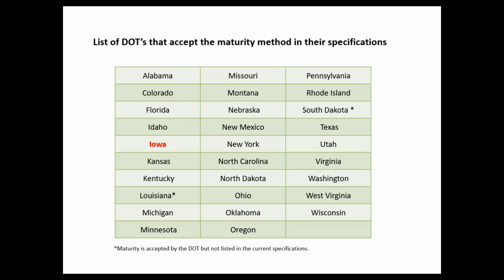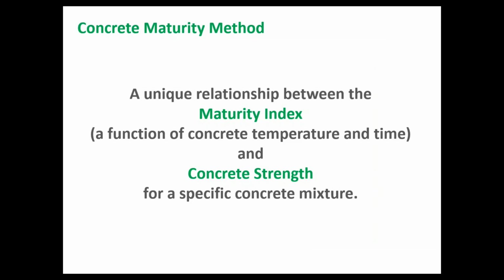Also, over the past 5 years, I would say more and more engineers are becoming familiar with this method and are accepting it. Again, they're getting confident that this method is working well, and they can gradually move away from field cured cylinders to these non-destructive test methods, and in particular, the maturity method.